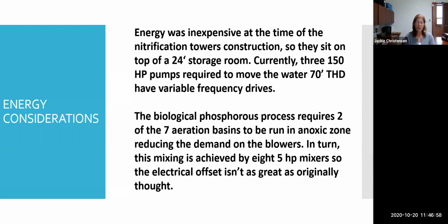One of the other energy considerations to take into account is, okay, 2 out of the 7 basins now aren't being fed by the blowers, so you think you have a dramatic drop, but you are adding some horsepower demand by adding mixers.